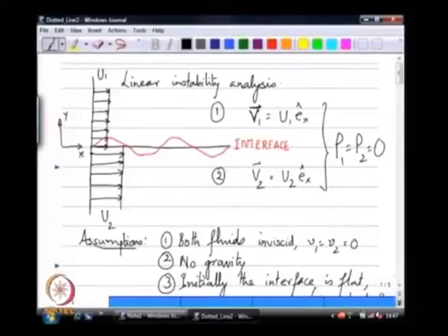We started to say that we are going to introduce a perturbation to the interface, and the simplest form of perturbation is a sinusoidal perturbation. We will see maybe later on why a sinusoidal perturbation is introduced, but essentially what we want is a set of harmonic functions, a set of orthonormal basis functions of the linearized version of the governing equations that I can use to take any arbitrary interface shape and express as a series of those orthonormal basis functions. This is simply going back to solutions of linear ODEs, in fact not even linear PDEs.